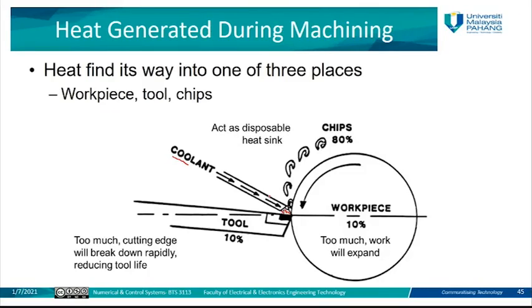At the end of the first operation, we have the coolant off. Then when we change to tool number two, we also give a command for the coolant to be on. Then at the end of the operation, the coolant will be off. The number of coolant on and off commands depends on how many operations the CNC needs to perform on the workpiece.